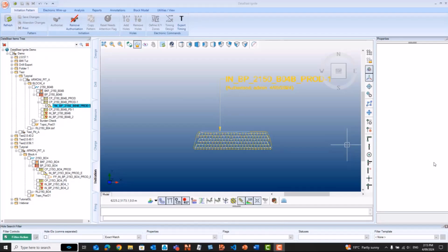That's from Tobin, 2013. As a rough guide, a scale depth of burial of 0 to 0.9 is a crater blast, and it's characterized as violent fly rock, air blast, noise, and dust with very fine fragmentation and good craters. 0.9 to 1.4 is a controlled blast with good fragmentation, maximum volume of broken rock in collar zone, acceptable vibration and air blast, and good heave and muck pile mound.